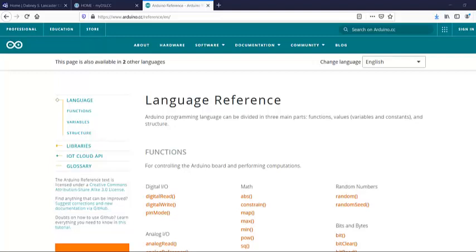Okay, we just had this lesson on pulse width modulation. And one of the questions was, what was the frequency of the oscillation between 0 and 5 volts? Now we know that it stayed constant, and what was varied was the amount of time that the function was on versus when it was at 5 volts versus 0 volts. So if it was, say, a digital or an analog value of 127, which is about half the maximum amount, it would be on half the time and it would be off half the time.